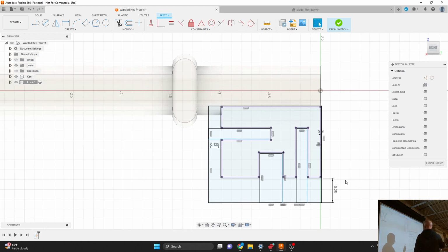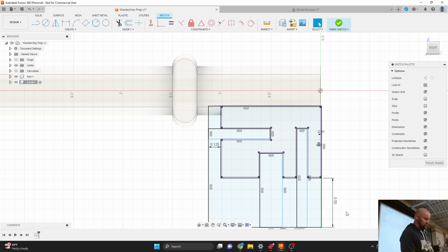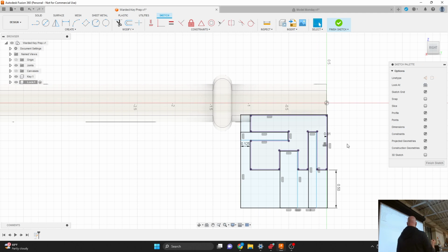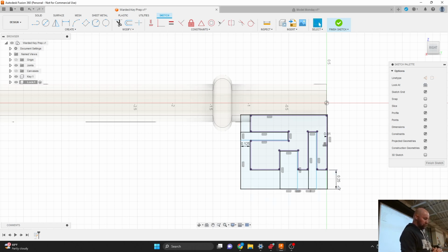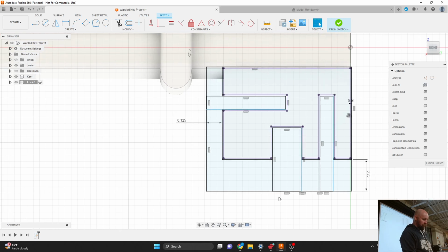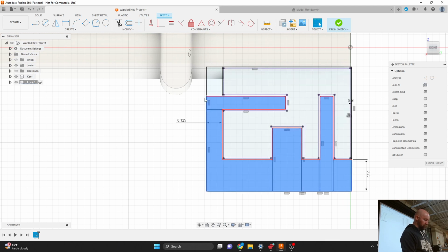And again, using constraints, using rules to put our rectangle in place, allows us to make this still easily changeable. So now if it's, hey, that's got to be a half of an inch, don't worry, those rules that tell the sketch how to be the sketch are going to be followed there. So less dimensions, more rules, kind of make things easier to change. All right, so that is our shape that we're going to revolve here.